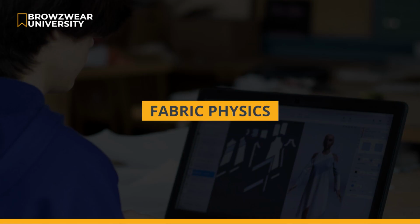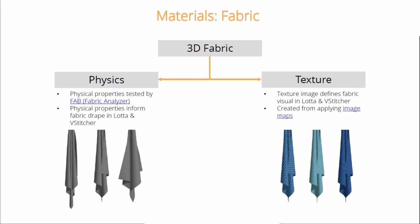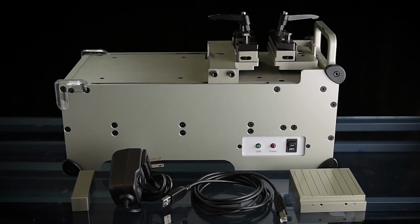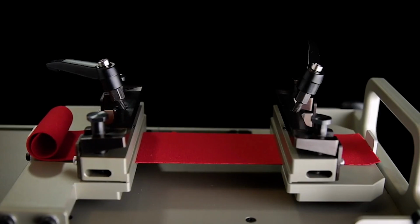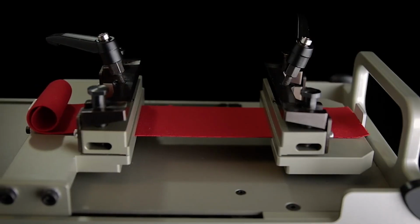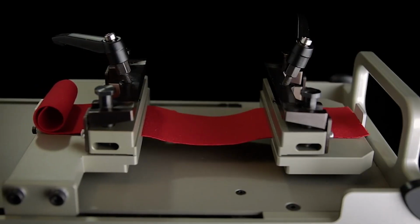In this video, we will be diving deeper into the physical properties of materials. A material consists of two elements, the texture image and the physical properties that decide the drape of the material in 3D. To capture the physical properties, we use the Fabric Analyzer by Browzwear, or FAB for short. Using the FAB, we run several tests on a physical swatch to accurately capture the material's physical properties.